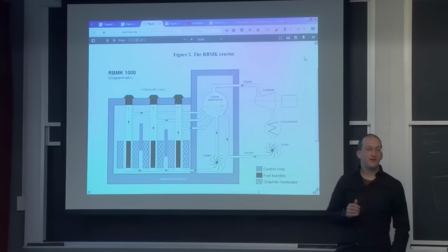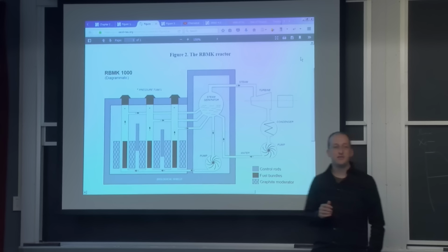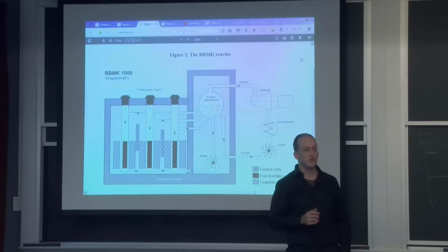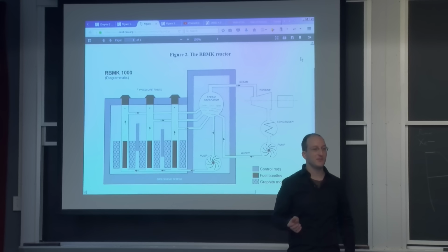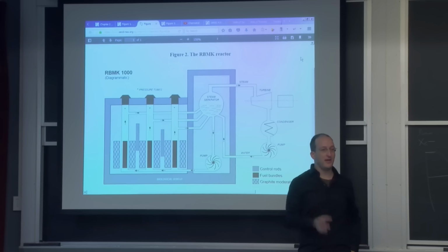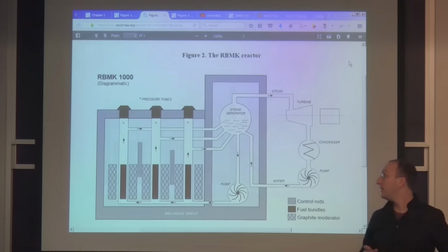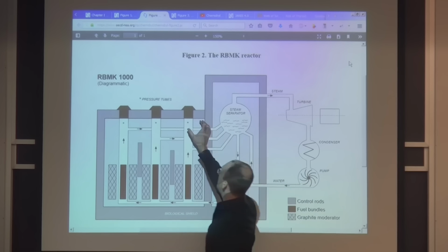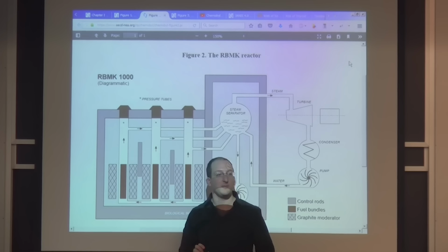In addition, they decided to disable the ECCS, or the emergency core cooling system, which you're just not supposed to do. So they shut down a bunch of these systems to see if you could power the other ones from the spinning down turbine. And then as they noticed that the reactor was getting less and less stable, they had almost all the rods out. Some of these pressure tubes started to bump and jump.